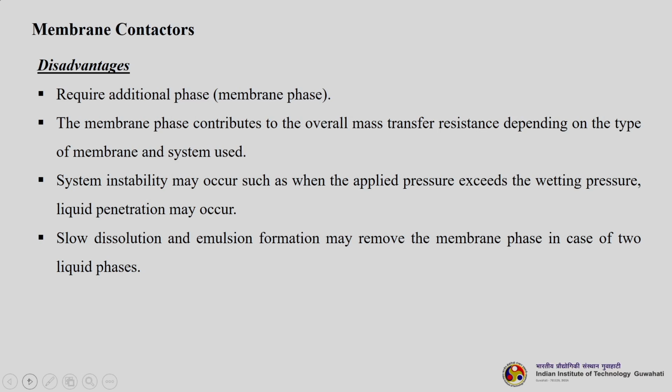Slow dissolution and emulsion formation may remove the membrane phase in case of two liquid phases. When we are talking about two liquid phases, if one is a gas phase and another is a liquid phase, then it is fine. But when there are two liquid phases, if they are mixing and forming some emulsions, then it may create an additional problem.